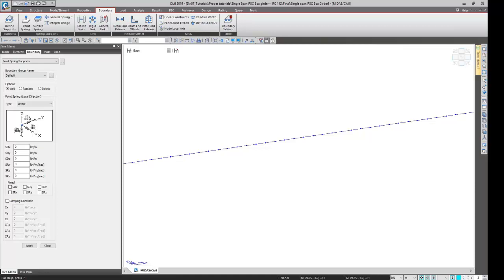But again, this is some value that could be easily obtained from preliminary soil analysis, maybe some soil test that is performed on the site, and we could input it. Or we can take some notional or accepted values of your soil subgrade reaction, which is generally for clay and those, and perform our first analysis, that is the preliminary analysis.